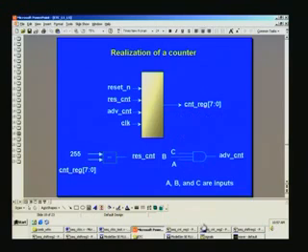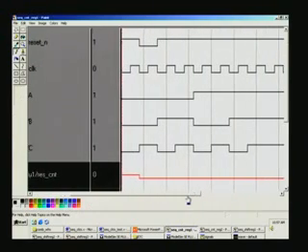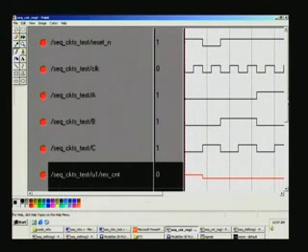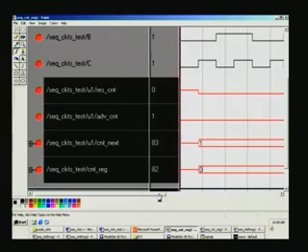That you'll be seeing in the waveform here. So the waveform for the counter, there are two waveforms here. The first one is based upon ABC condition. If A bar BC bar is encountered, what happens here? So you have counter next, counter reg here, and once again you see it's a multi-bit precision, and it is in decimal here. So it has been put as decimal. We'll see that in the ModelSim later on.